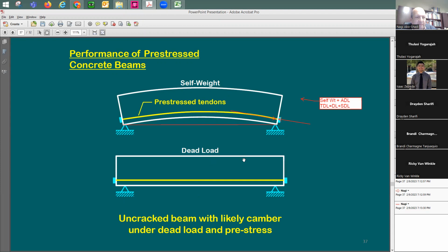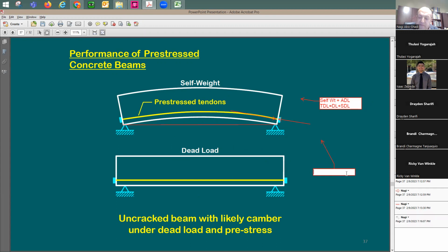Just to be safe, when you put this pre-stressing, you put enough pre-stressing so that you'll make this flat. And because of this uncertainty, maybe you'd like to stress it to balance, which means to bring this force down, right? You'd like to balance, I'm going to say maybe 75% of the dead load, right? Now, which dead load? Total dead load? You say yes, total dead load. Let's say to 90%.